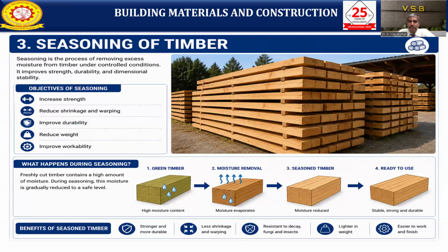What is the benefit of seasoning? The timber will be stronger and more durable, with less shrinkage and warping, and resistant to decay, fungus and insects. These won't occur if you do proper seasoning. It is also light in weight, easier to work and easier to finish.